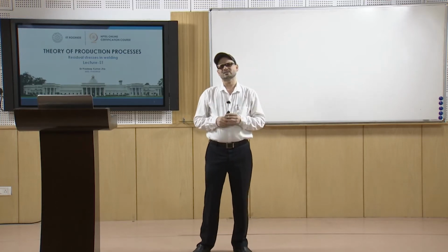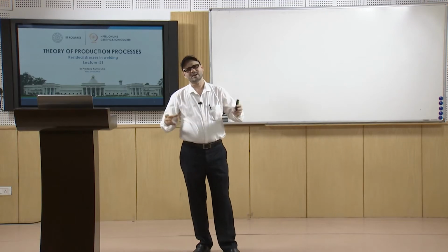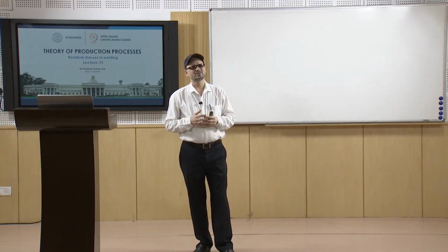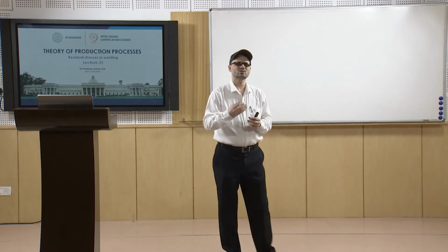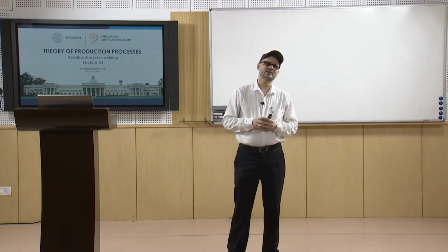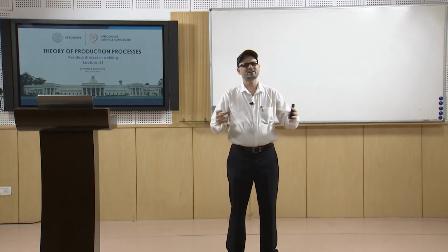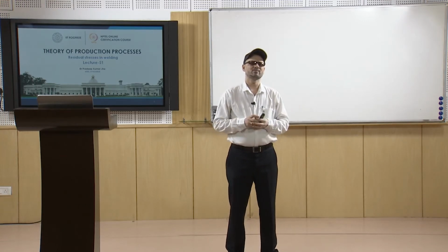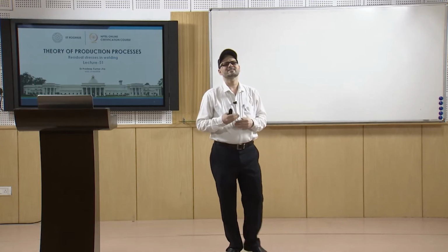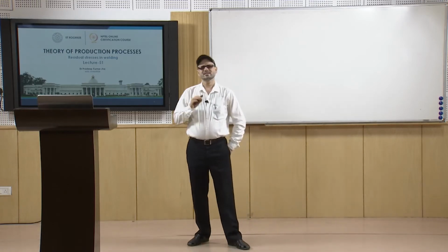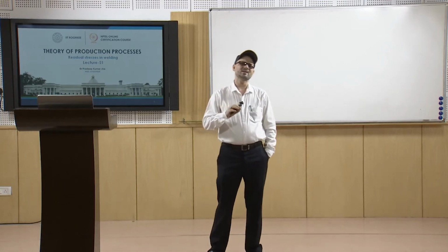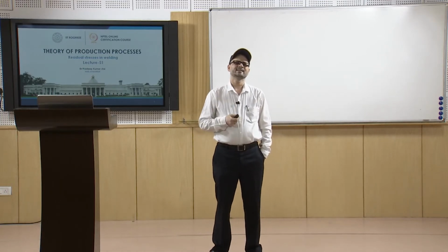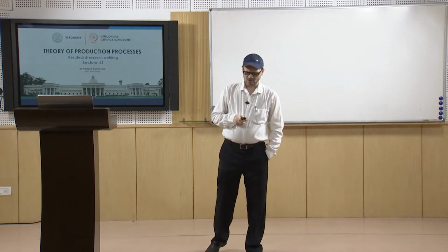Because of that, and also because there are other parameters and constraints, like the larger cooling rate and restraint because of certain types of members, the stresses are developed, and these stresses are locked inside the material. So, they are basically known as the residual stresses.